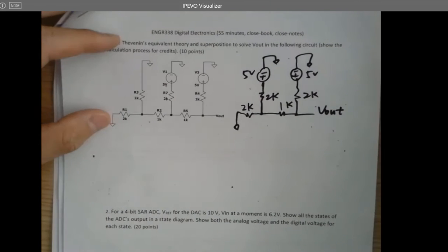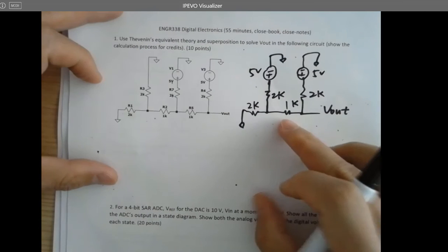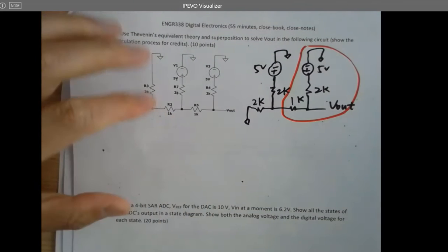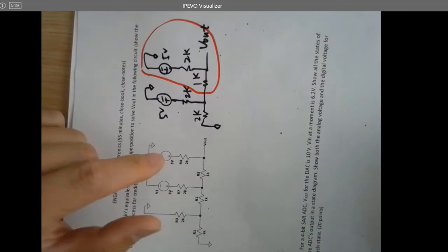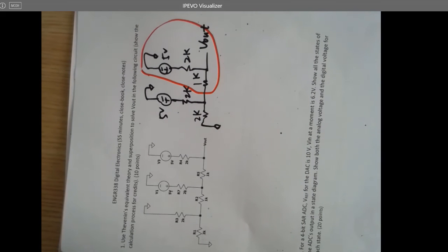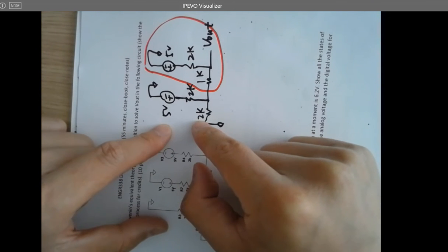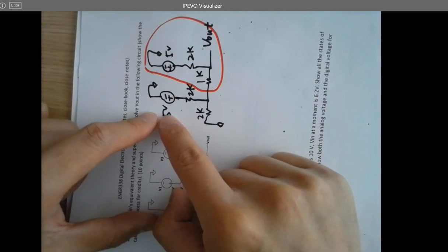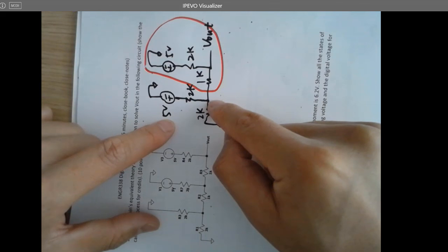All right. And when you are looking at it, just treat whatever here as the load. That's a load. So that's the voltage divider. You know, since you guys have learned Thevenin's equivalent for so long, you can find out it's actually super important and useful. And if you have this kind of circuit, and people are asking you what's the Thevenin's equivalent, what is it? Yeah, 2.5 for the ETH. Why? Because this is a voltage divider, so whatever voltage here will be the ETH.